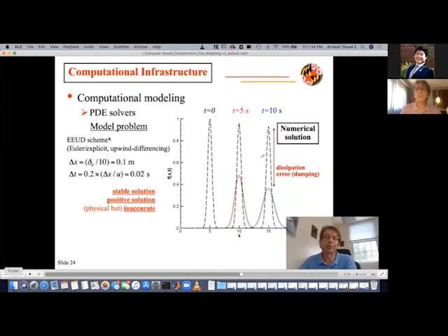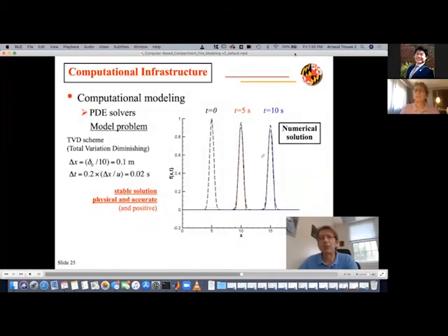And finally, today, thanks to applied mathematics, you have schemes that are much more elaborate. This is an example of the scheme adopted by FDS. This scheme is called the TVD scheme, using a total variation diminishing approach, and this scheme is both stable and accurate.